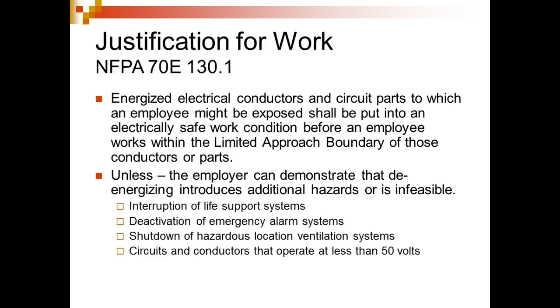If you put it across something, what did you just do? You shorted that sucker out. If you put it across the circuit, then you just created a short circuit, which is bad. So these things are fused, but you got to understand fuses don't act instantly, right? You understand? And all it takes in a high voltage circuit is just a little arc.